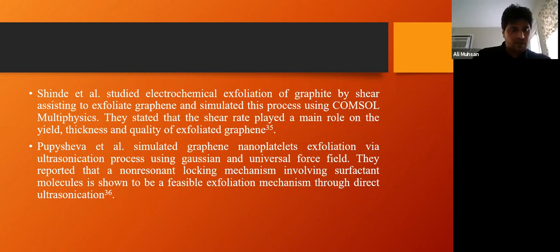And another work done by Babaevsky et al. simulated the graphene nanoplatelets exfoliation via ultrasonication process using Gaussian and universal force field. They reported that a non-resonant locking mechanism involving surfactant molecules is shown to be a feasible exfoliation mechanism through direct ultrasonication.